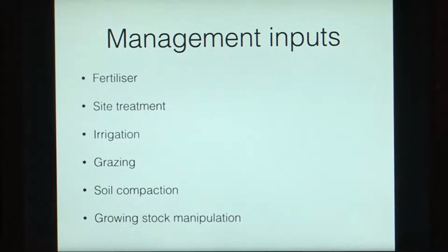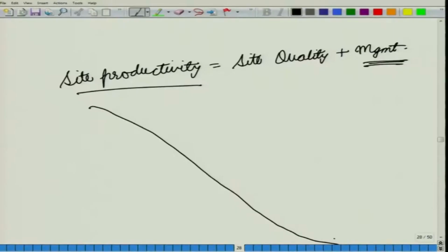You can put on irrigation, or for instance, in the same soil you can put on say check dams or contoured trenches. If you put up a check dam or a contoured trench, suppose this is your slope, and you have put up some bunds like this. The water that was flowing through will get accumulated at these points and will later be seeped down. When that happens, the water table of this area will slowly increase.